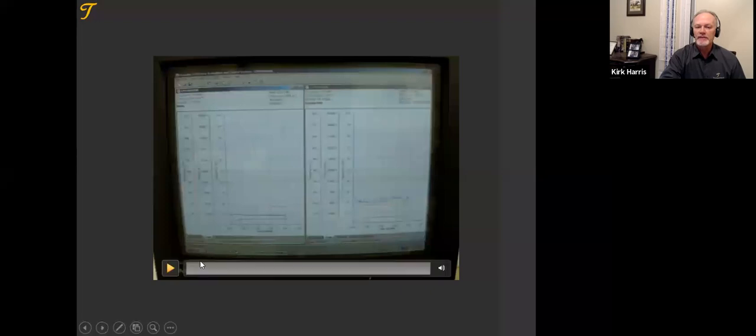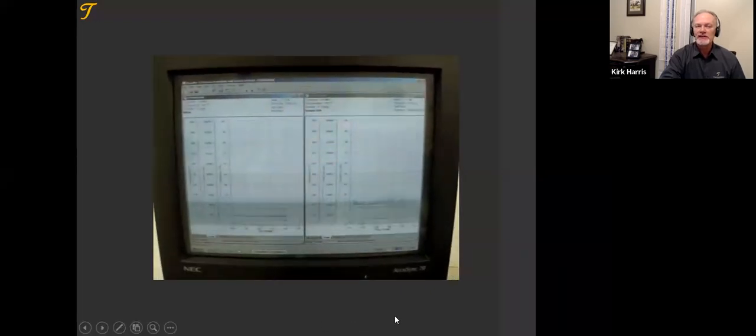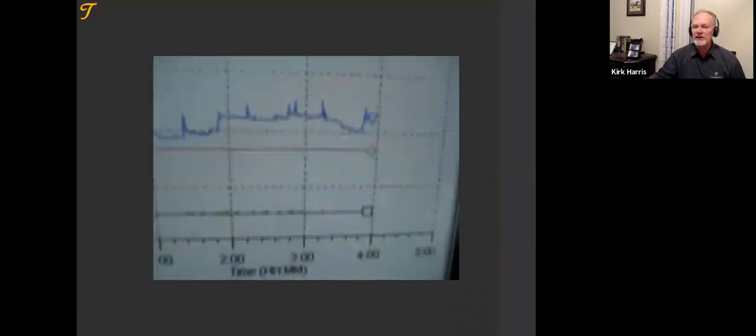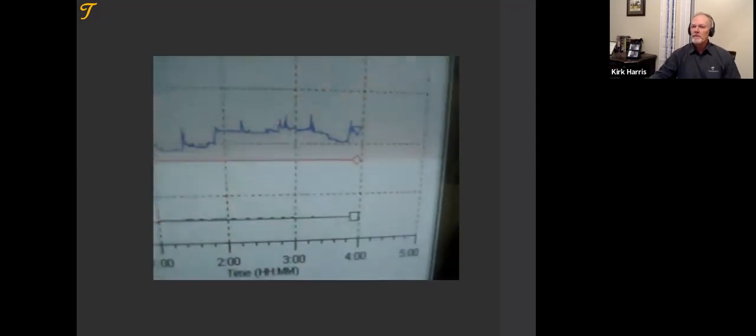And then we're going to monitor our thickening time. We'll see the variable blue line there. That's our consistency. When it reaches a certain level, it could be 40 Bc, 40 Bearden units, 70 Bearden units, 100 Bearden units, we call that the thickening time. Right down here now, it's at 20. When it heads up and reaches 70 Bearden units, about 90% of the world uses 70 Bearden units as the cutoff for thickening time. For lightweight cements, we may use 40. When we're testing API specifications for cement, it may be 100.